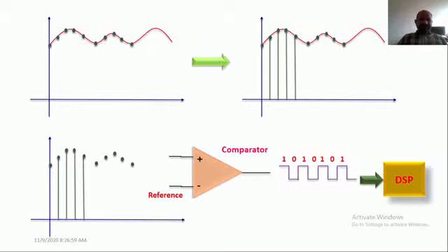So sample is nothing but the sample information. These dots are the sample information. Let us suppose, if you see this one, we have the sample like this. But if you want a clearer picture, then you are supposed to take more samples. I am not interested in losing the information between these two samples, so I'll increase the number of samples. If you increase the number of samples, you are going to get more clear information about your analog signal in the discrete format.